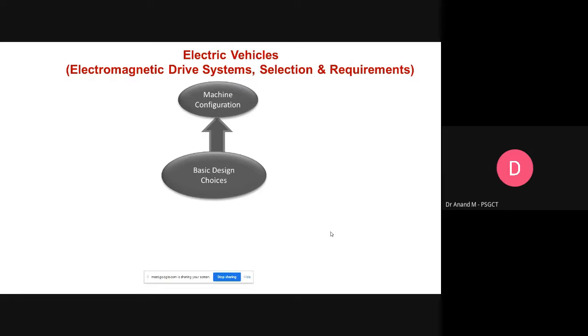So can I go for a PMSM drive system with the rotor placed interior or exterior? What type of magnetic configuration should we build into the PMSM drive, and how are the stator, the stationary part, and the rotor geometrically defined with respect to the volumetric constraint for the given D and L? How can we configure the machine? That's the first designer's choice.